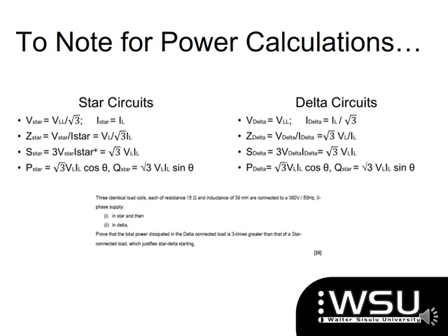That's the first thing. Then the second thing, if you are in a star connection, all right, you must remember that the 380 you were given is your line to line, because we always assume that you're given a line to line voltage. So your V star would be your line to line over your square root of 3. Okay, and your I star, we know that will still be the same as your I line.